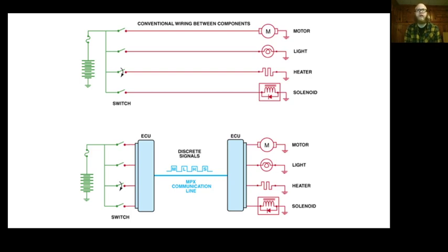So this is just the plain circuit engineering that's built into that little computer board. The next thing it looks at is its read-only memory. It works a little bit hand in hand with the way that the board is actually structured and the chips, the little processors that are built into it. The read-only memory can't be changed. Between the structure and the read-only memory, this is the main reason why a powertrain control module is a powertrain control module only, and a body control module is just a body control module.